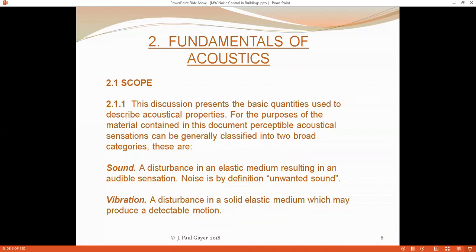The barrier, typically in building design, is going to be a wall, floor, ceiling, some solid material. And the vibrational energy from the air molecules in the source room is transmitted to the barrier, the wall starts vibrating, you might say, which then sets the air molecules in the receiving room into the vibrational mode.